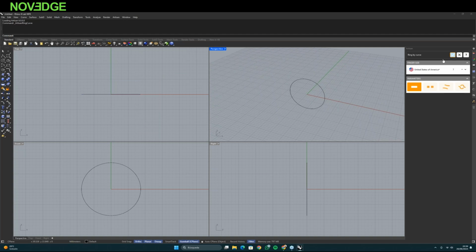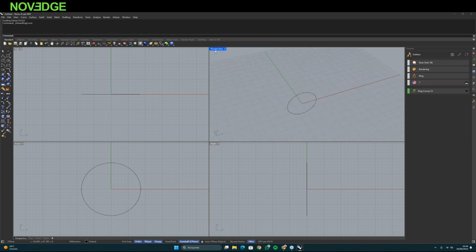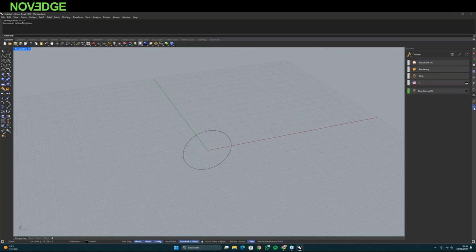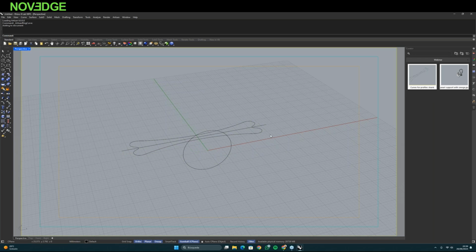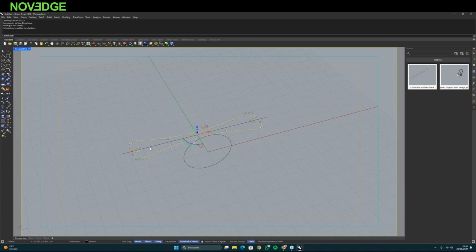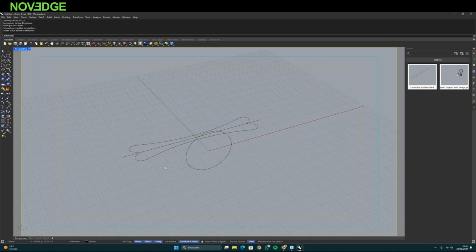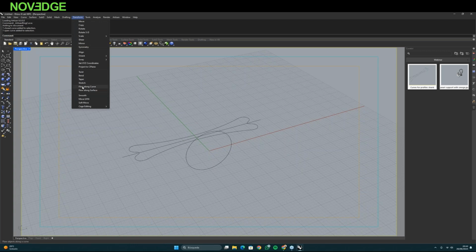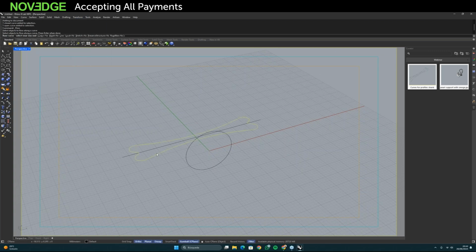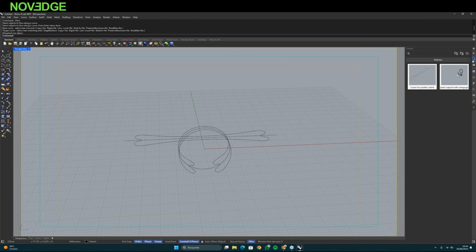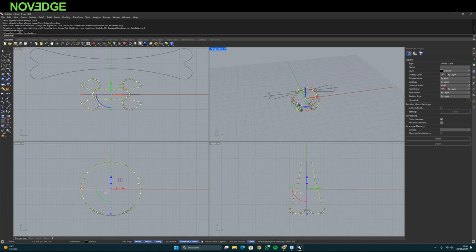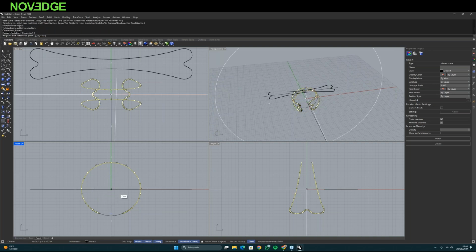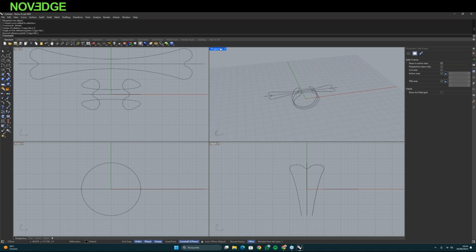I always like to make this curve. And for this occasion, I create some curves that I added here on the Creator tab. I created this folder to keep my things saved there. And I call them here. And I create these curves that I'm going to flow on this other one. For that, we are going to use transform, flow along curve. Select the curves that we want to flow from this curve to this other curve. So let me remove this frame here. Yeah, okay. So I'm going to rotate it. Okay, we have the curve ready.